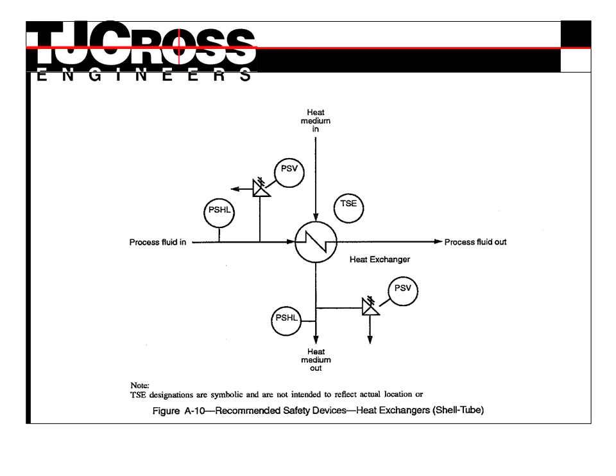Appendix A contains a typical drawing showing the safety devices, a safety analysis table, or SAT, for each process component, and a safety analysis checklist, or SAC, listing all recommended safety devices and conditions under which a safety device can be excluded. This concludes our training module on API RP14C.